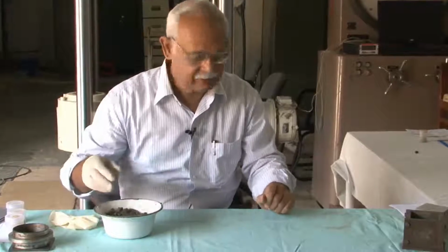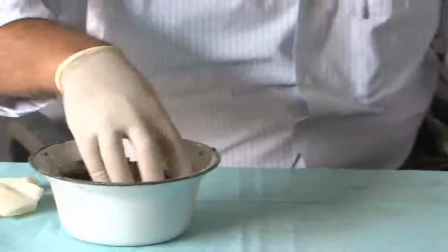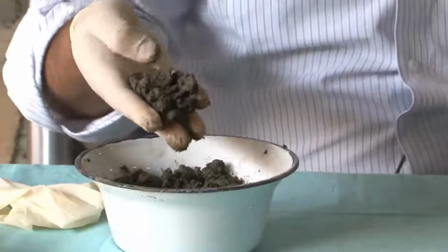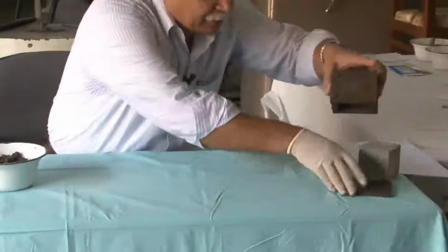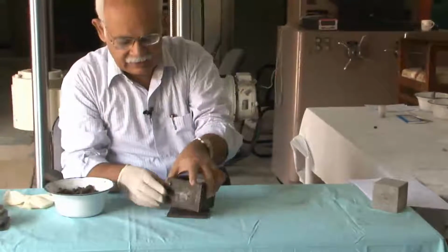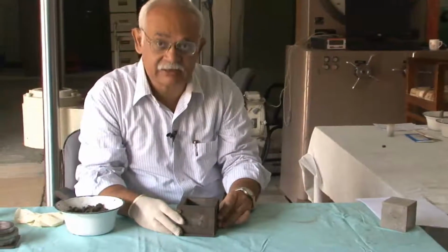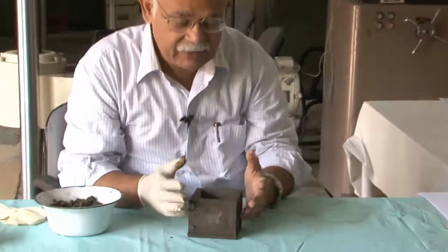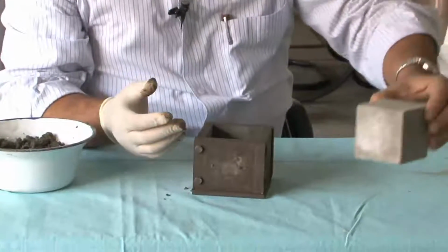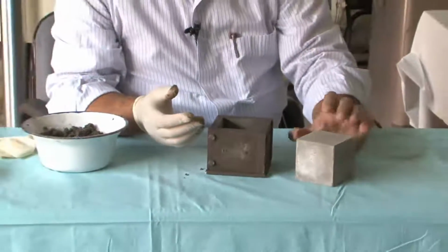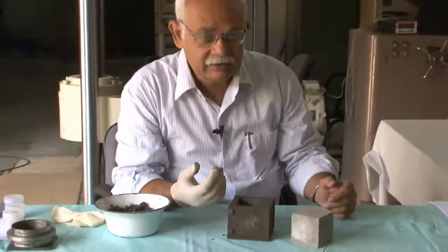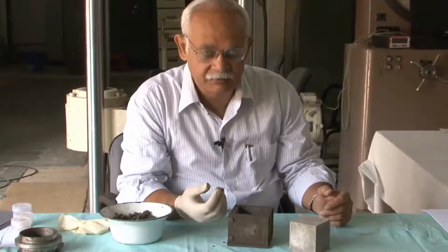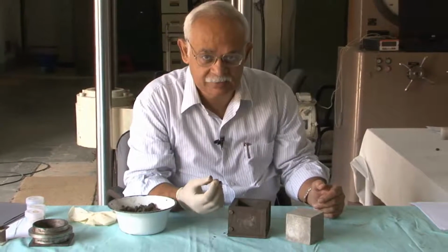Strength of cement is determined using mortar, and this is a mortar sample that we use, and what we do is to fill this mortar in a mold of a certain size, which is something like this, and what we get at the end of it after it has hardened and so on is a cube which is something like this, and these cubes are tested for strength and we get a value for the strength of the cement.